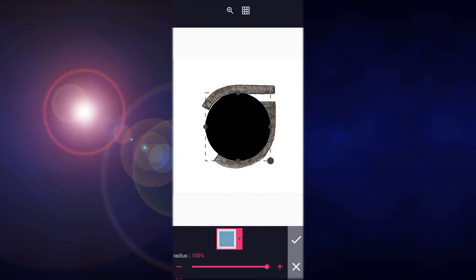It will move to one side and the other. But instead of that, if you select this triangle and increase the radius, it will automatically be centered. That's the reason why whenever I want shapes to be at the center, like this round shape, I always select the triangle, then use the radius to make it a circle so that it can position to the center.